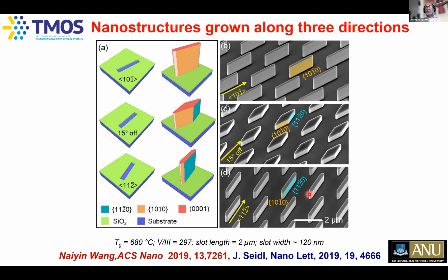So now you can see that instead of just making nanowires, we're able to make thick membranes, thin membranes, and diamond-like structures. It really opens up lots of opportunities. In fact, we have used these nanomembranes and demonstrated some nanowire transistors in collaboration with Professor Adam McLeich's group at University of New South Wales, for example. Okay, so people have demonstrated nanowire transistors as well, but I will not be focusing on the transistors in this talk because the talk is really focused on optoelectronics.